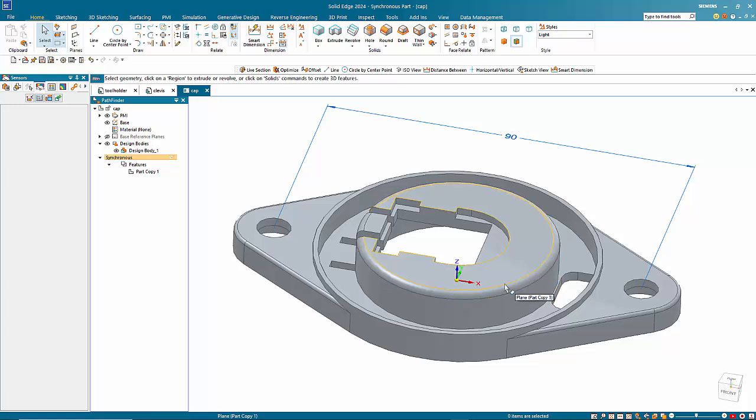So one of the things that can get a little bit tricky is just the ability to, if I click on a circumferential face, I can change the size, but we're going to run into this hole. So we might want to make sure that as we make a change on here, it will move this out to allow for it as well.